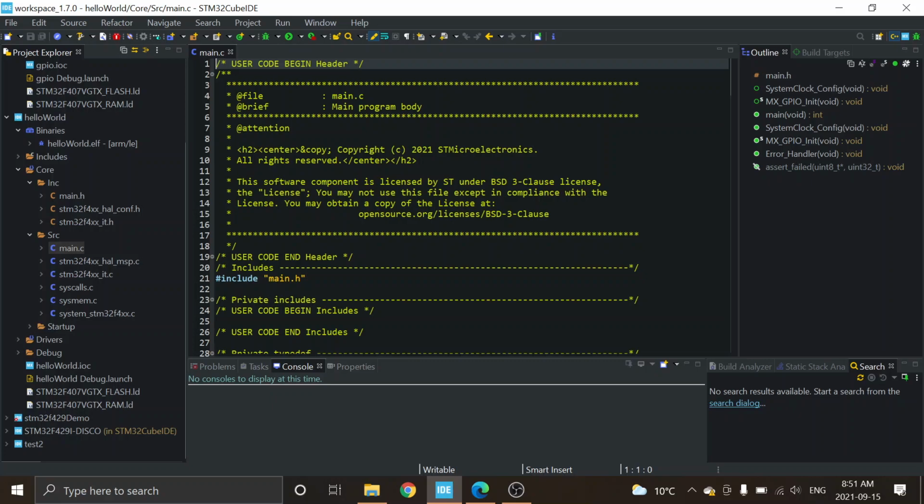Well, I want to use the math library, so I want to include math.h. So the first thing I do is put include math.h right underneath main.h, and that's awesome, and it compiles and it all works. And then I add the blue button in the graphical environment and I go generate, and then all of a sudden stuff isn't working because it wiped out the include math.h because it wasn't where it should be, because I put it where I've always put it.